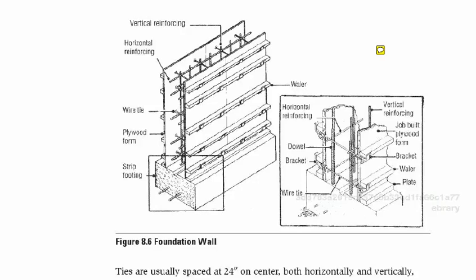as you're looking at the work and scheduling time, it takes carpenters a while to build something like this. You also don't often do a whole piece of wall or a whole structure one time. You do part of it because you're limited by the size of the lumber that carpenters can handle. And remember, sheets of plywood, a 1-inch sheet of plywood or 1.5 inches, whatever you're going to be using, is a heavy piece of material, so you can't expect them to handle more than a 4x8 sheet at a time to be able to put things together. That's part of your job, though, is to schedule that work and to consider what the carpenters can do.